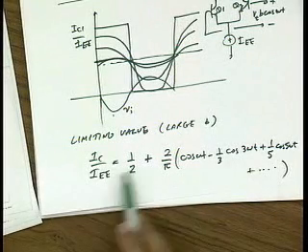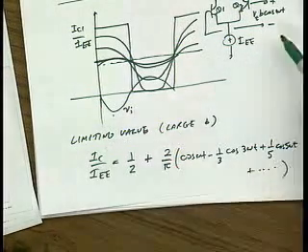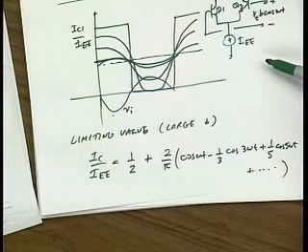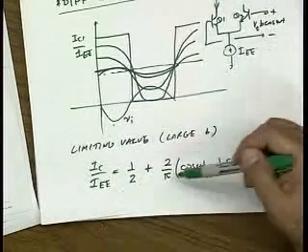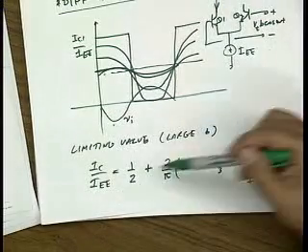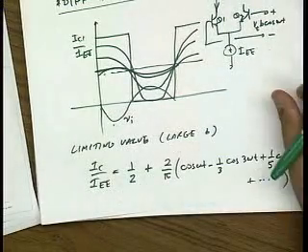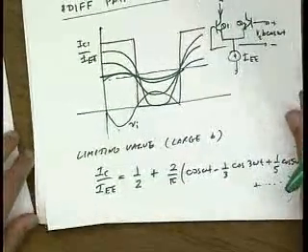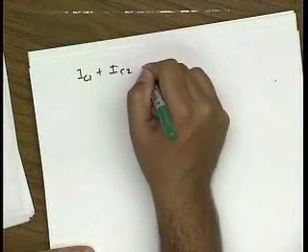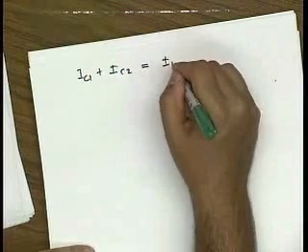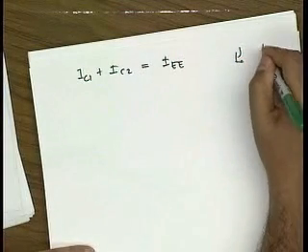Now, even though this is the limiting value, it turns out that if you put a few hundred millivolts across this differential pair, you get pretty close to this squarish waveform. And this is very convenient for doing simplified analysis, hand analysis. Okay? If you want to be more accurate about it, you could just write down a few equations. You would say, okay, I know that the sum of the collector currents have to equal IEE for a diff pair.